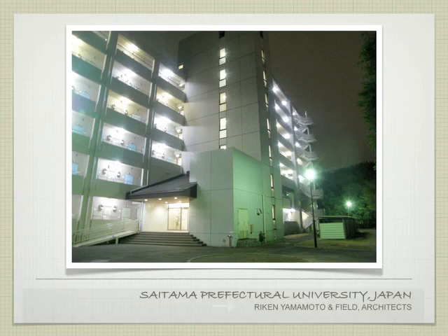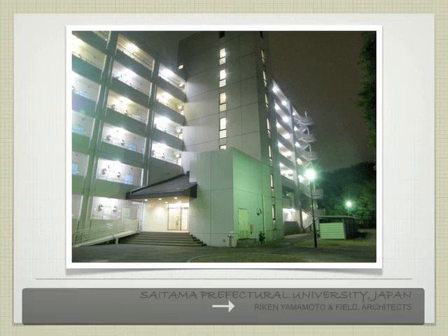From this side, right, we see the same thing, right? Each of these can be a precast element, right? This column can be precast. These wall panels can each be precast, right? The stairs and stuff were stuck on the outsides of this building, so they were easy to prefabricate in steel, right? So you kind of get the theme of this was designed to go up as quickly as possible.